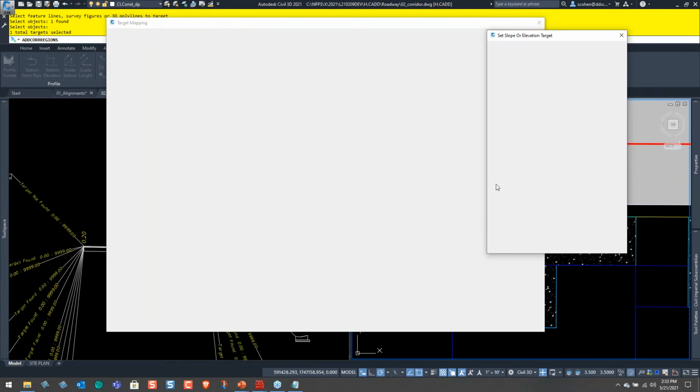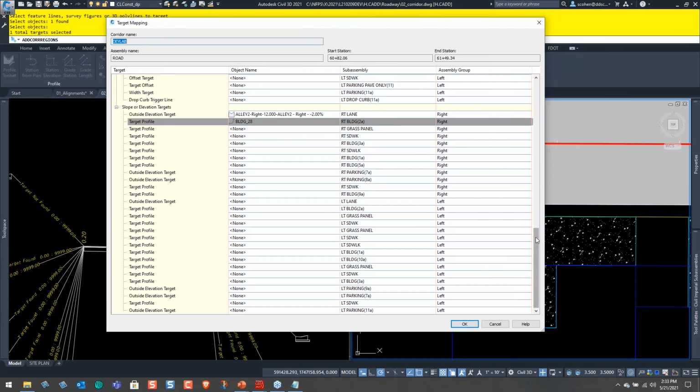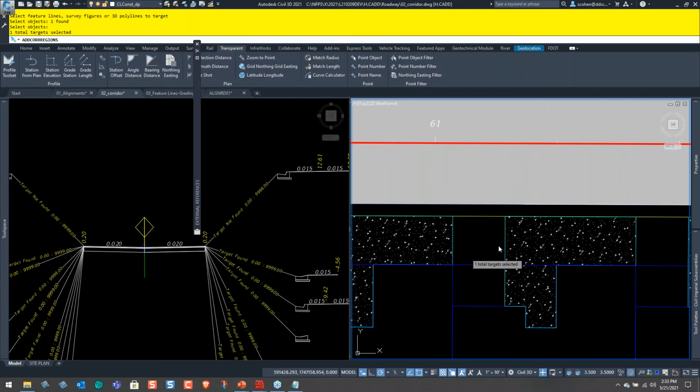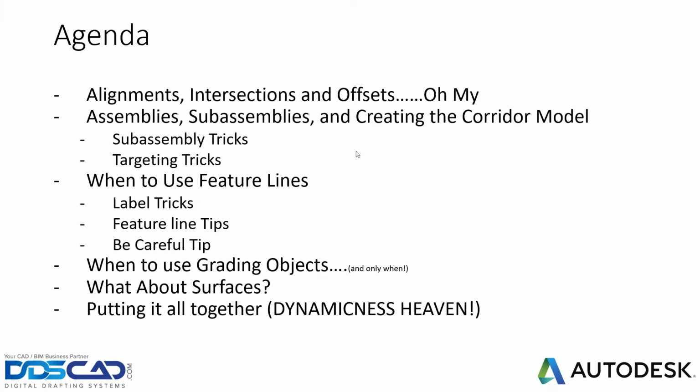Basically, what I would have done, just so you know, initially I would have just done the curb, and then I would have gotten the elevation, and then done a rough calculation saying, hey, that's 7 feet times the grade, 0.015, or 0.02, whatever I want it to be. I start with that. The distance times the grade gives me an elevation, add it to the elevation, and that gives you an idea of where you want that to be. And then I'll just hit OK here. And now it will add that targeting on that side, and it will target this horizontally, vertically, and it will actually show me the grade inside the actual road as well, okay?